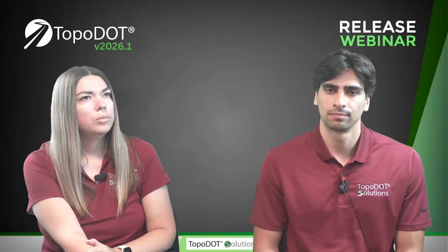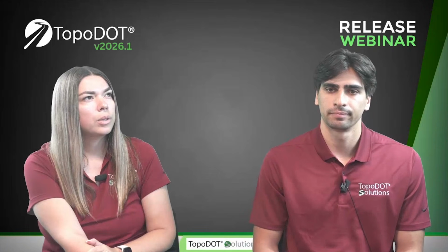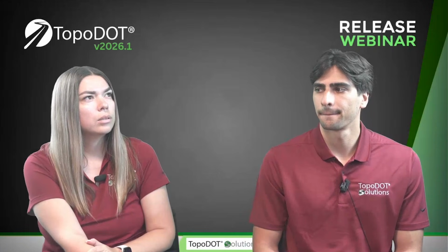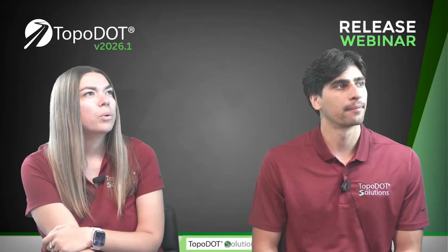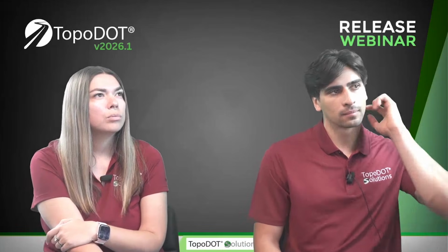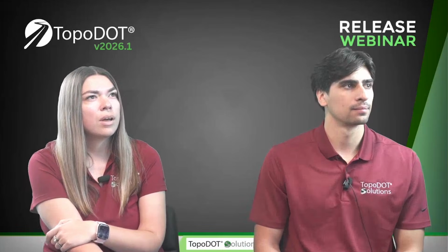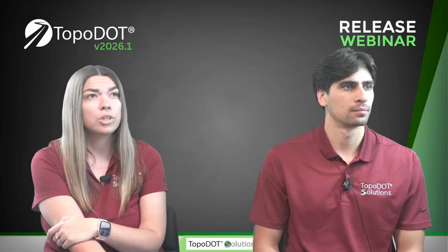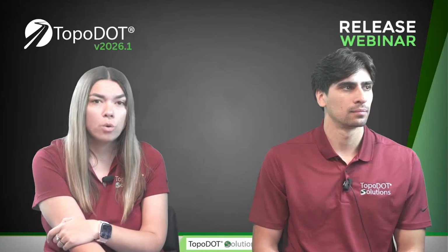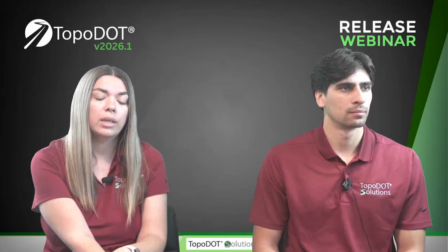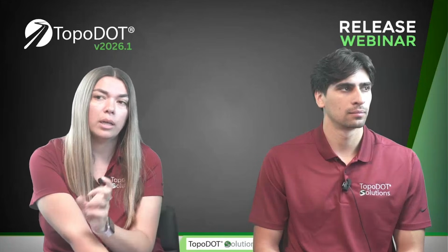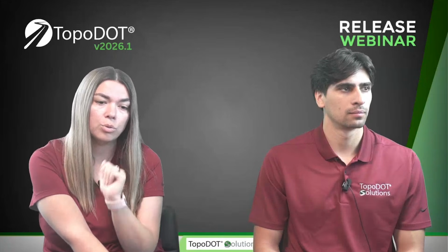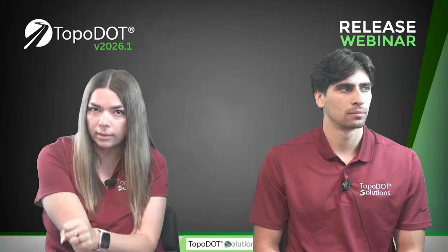Next question. Jack asks, with the quick adjust tool, can you merge elements that are on different MicroStation levels? Nope, you can't do that. They need to be in pairs. And I'm not even sure why you would like to do that.